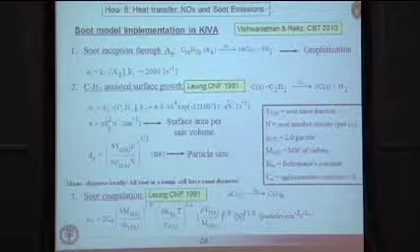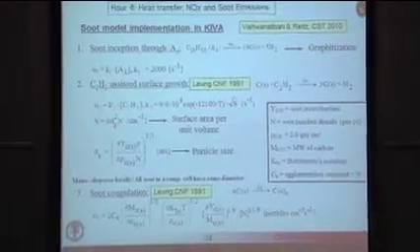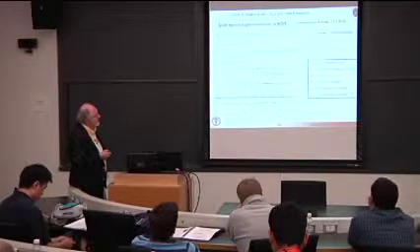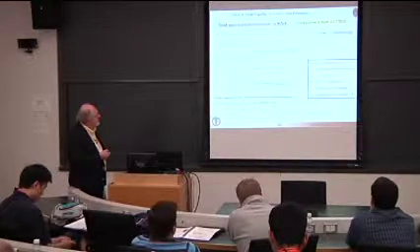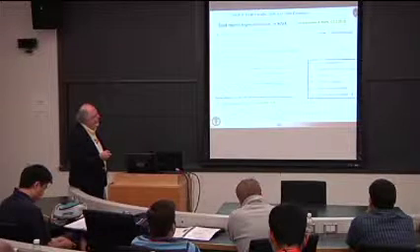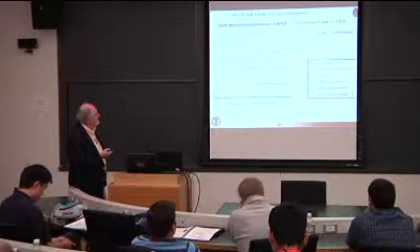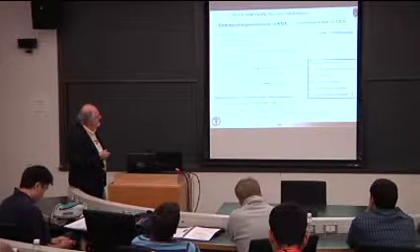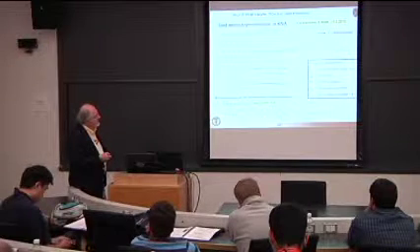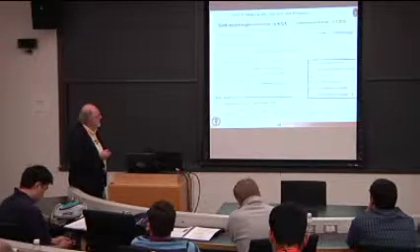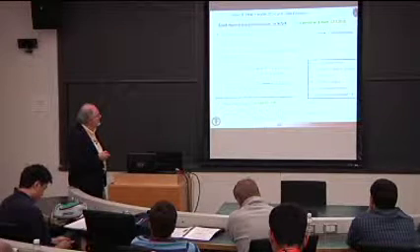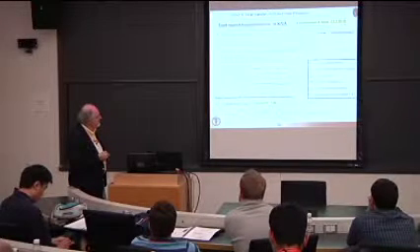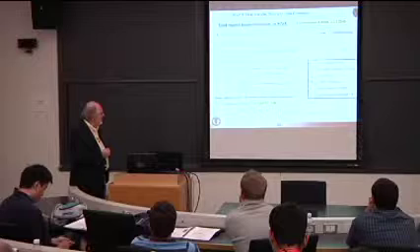So this describes how we implement the soot model in our CFD code. Basically, we start out with soot inception, where we start from the pyrene, the A4, and with a certain rate taken from the literature, we produce the first soot or carbon particles, or graphitization. Then we have acetylene-assisted surface growth, essentially acetylene combining with whatever carbon you've created here as your soot contribution. This depends on the surface area of the soot, so we have to track the surface area. For that, we need to know the soot diameter.